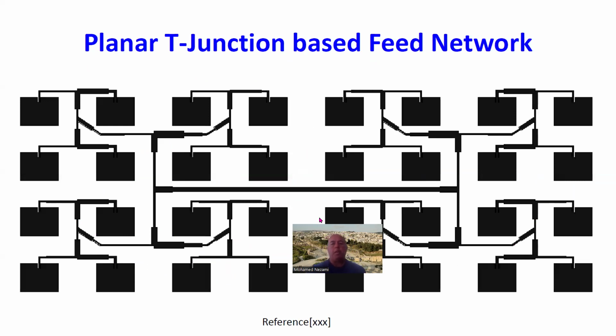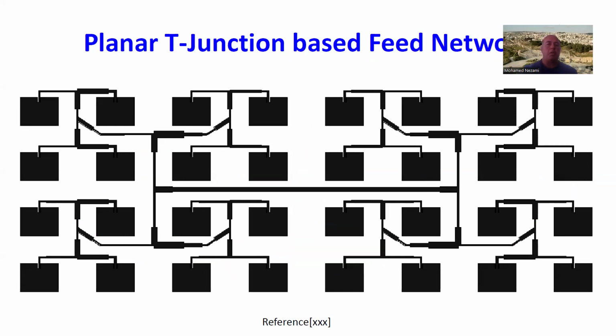Okay, so basically antenna array networks, like the ones we have covered in the past 3 sessions, which you could go back to. Most of the arrays present nowadays in research and in manufacturing are really based on the use of a T-junction splitter. That's basically starting out right here where we feed the signal, we split off with a T-junction in here for this subarray, and then we split again with T-junctions, and in here you can see that the impedances are different, which means the power levels are different between this subarray and this subarray.